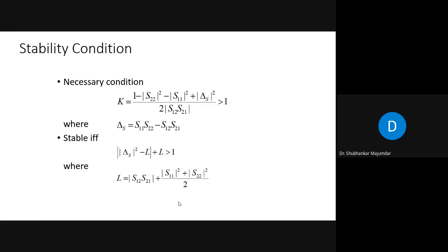This is the range. When you are doing a simulation, you have to see that your system should be stable from 1 gigahertz to 8 gigahertz. Then only you can claim that after fabricating, it will be stable at 2.5 gigahertz to 5 gigahertz. This is the thumb rule. When you are designing any circuit, we have to be very cautious that the simulation results should be far better at higher frequency ranges. Getting my point? Yes, sir.